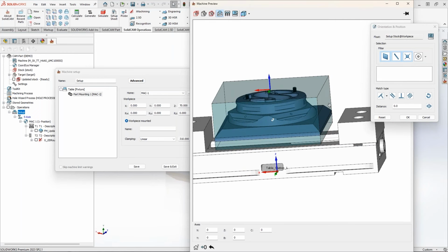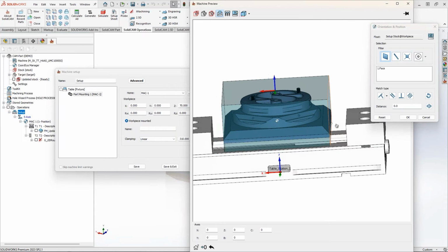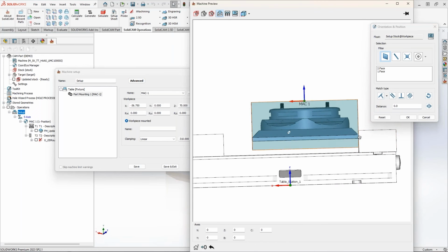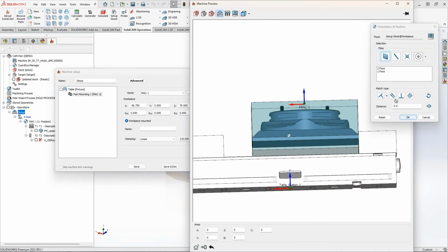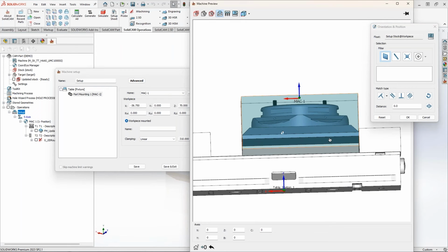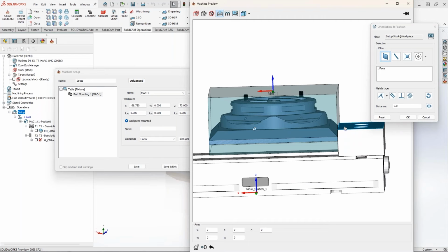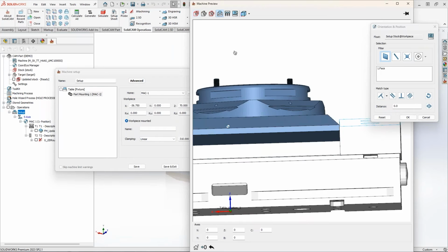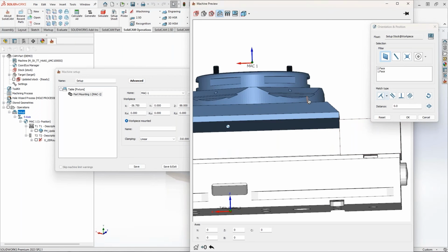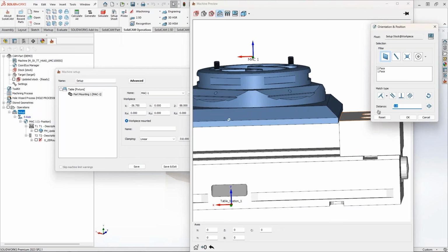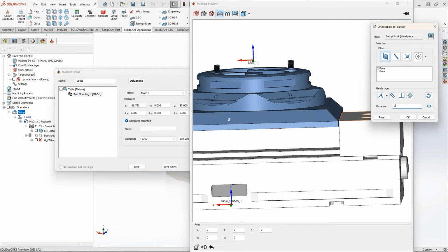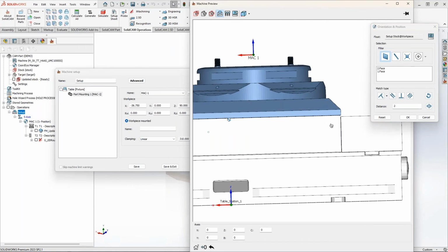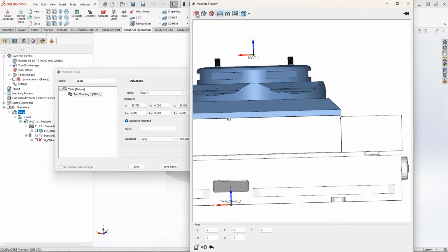In this demonstration, I'm just going to click on the faces, click on this, click on that. The faces are listed. Let's do match. So I'm going to do the following: I will delete this selection, and I can say I want to go from this point, maybe for the bottom of the part. I'm going to hide my stock, click on this, and just hit it. There you go. You can now, of course, put a distance of 5 or maybe 2, and you can also flip it. So you have here the option of flip, and it's going to flip. Click OK. There you go.